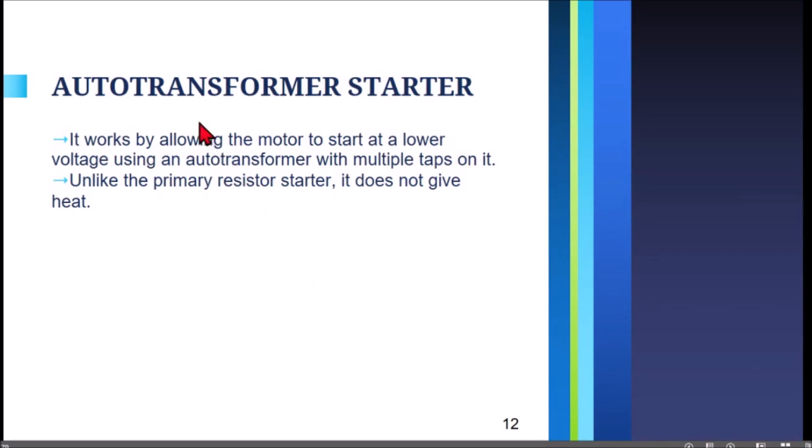Then we have the auto transformer starter. It works by allowing the motor to start at a lower voltage using an auto transformer with multiple taps on it. Unlike the primary resistor starter, it does not give off heat. Its only disadvantage is that the auto transformer is sometimes expensive.